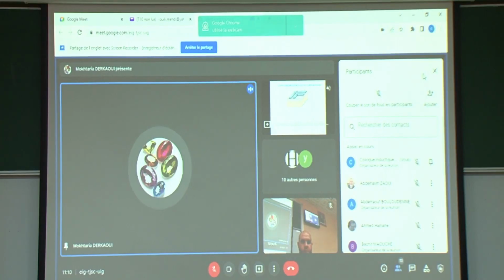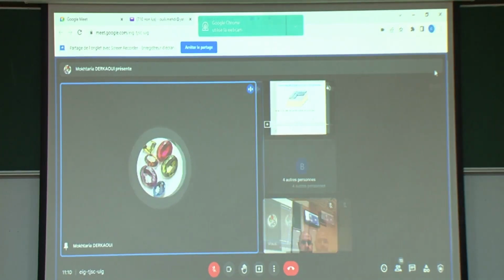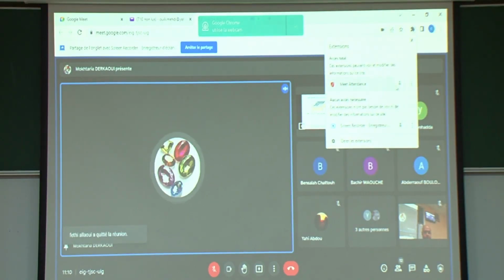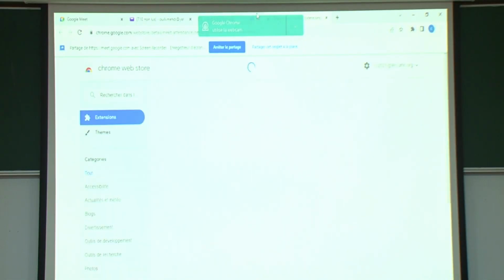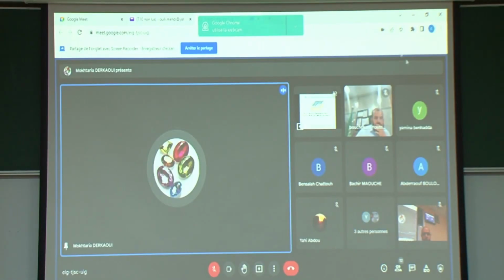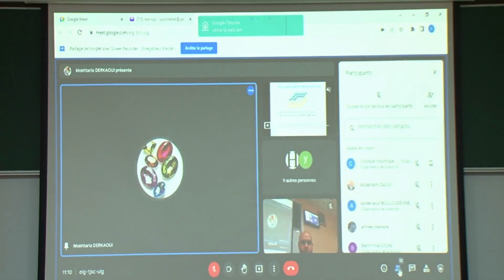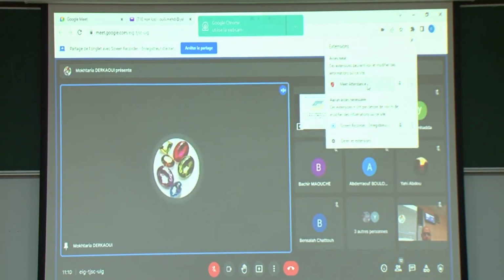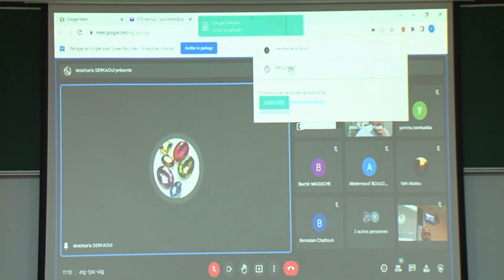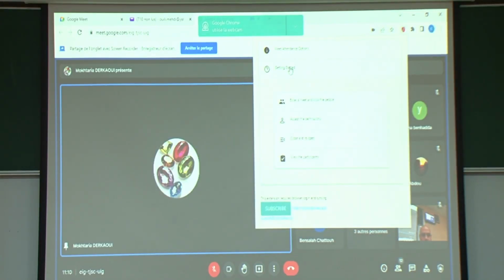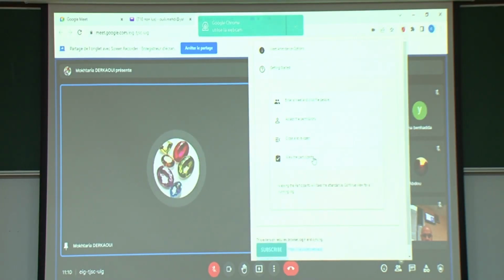The stack of different layers of different materials allows us to create different phenomena. We define E1 as the electric field between coils due to the ohmic losses, and E2 as the electric field between the coils due to the coupling capacity. E3 is the electric field between the spiral coils and the substrate due to the oxide and substrate capacities. B is the magnetic field due to the direct current circulating in the spiral coils.